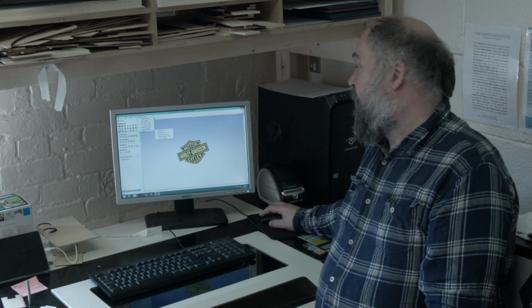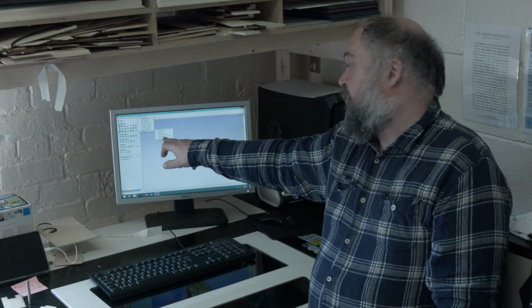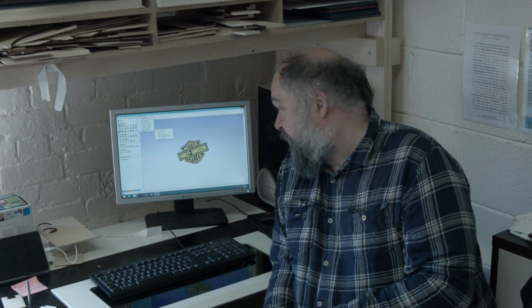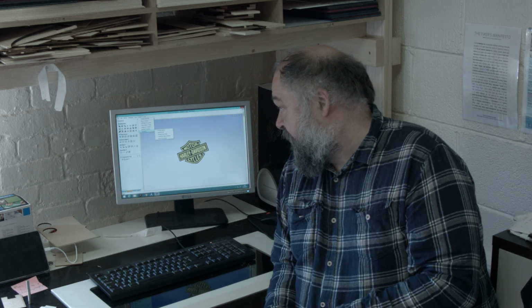So the wrapping, you've got fluting, spirals, wrap job setups. That's where you can actually unwrap an STL to it. So one of the ones they gave us as a demonstration is a chest piece. You unwrap it. The problem is you get a slight seam down the back. It's not perfect, but again, it's something that can be sanded out. Yeah, it is. Sweet. But not a full package. But when you put it straight out to the CNC, it's fun.